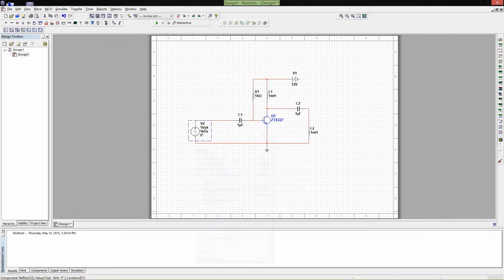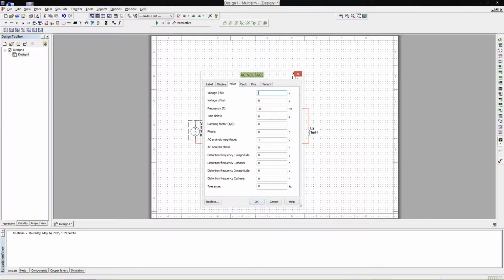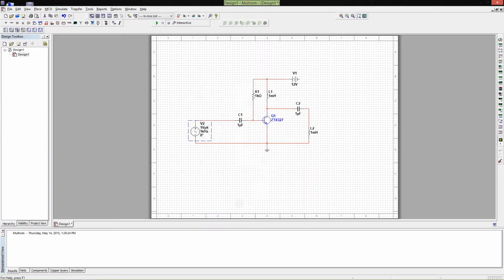Alright children, now it's time to change the components to their correct values. These values were chosen at design time according to the transistor data sheet. Don't forget correct letter values when it comes to components, such as capital M, lowercase m, and lowercase u.